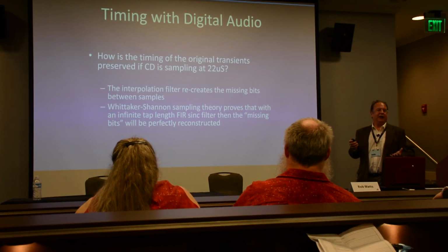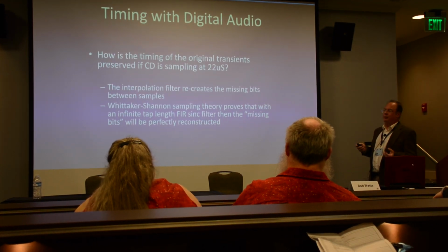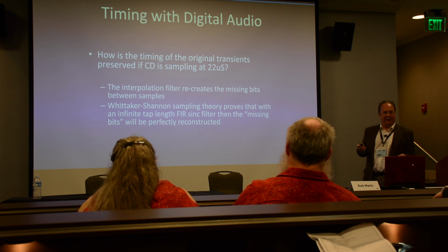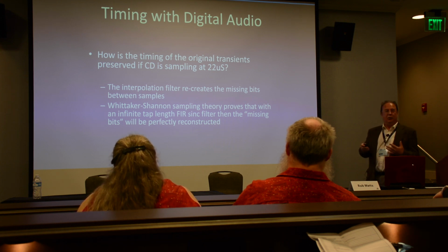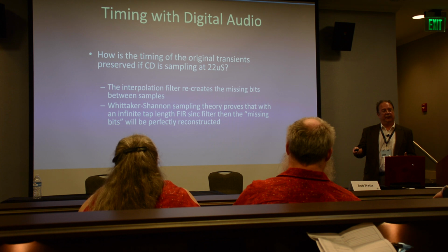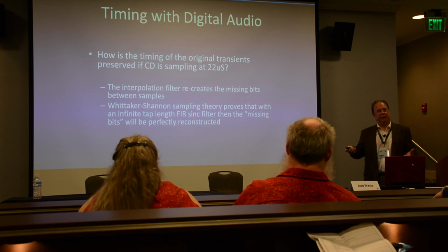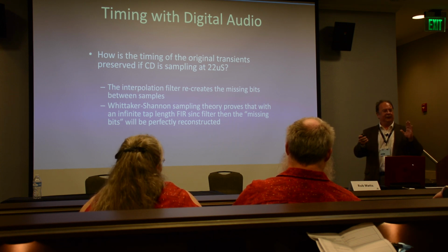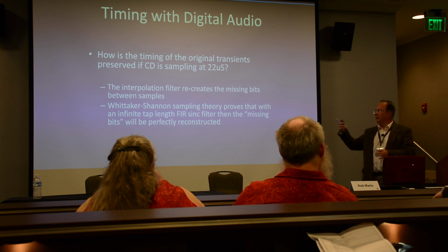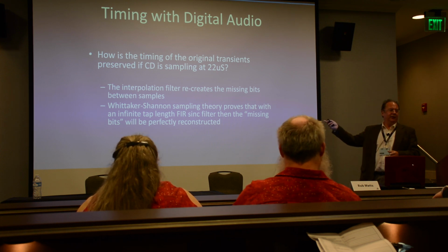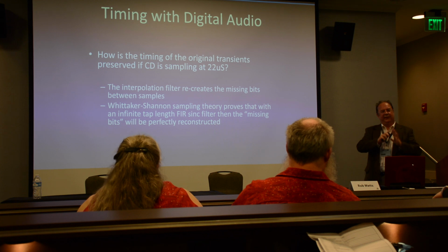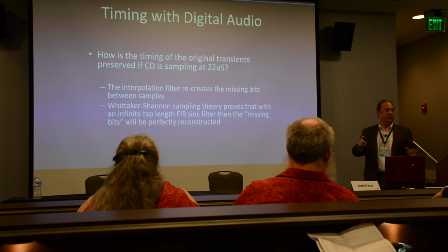There's a theory called Whittaker-Shannon sampling theory, and this proves that if you have an infinite tap length FIR filter, you will perfectly reconstruct that signal. It will be no different whatsoever. You could be sampling at 22 microseconds, use a Whittaker-Shannon interpolation filter, and it will be exactly the same as if you were sampling at 2 picoseconds. You would get exactly the same waveform.